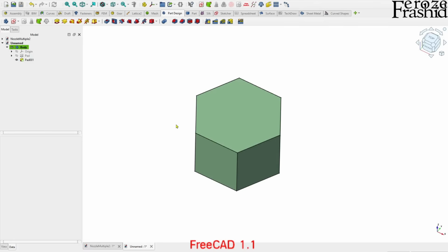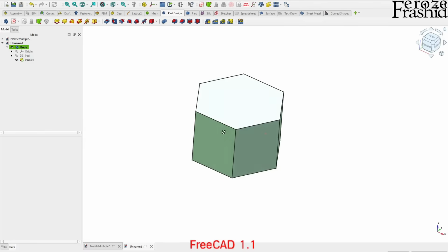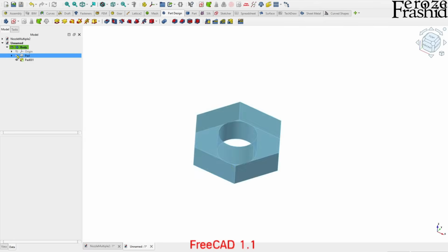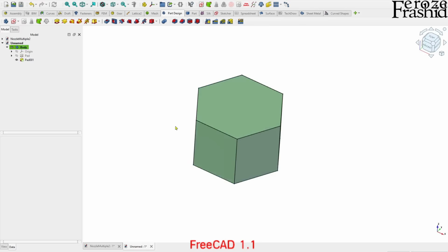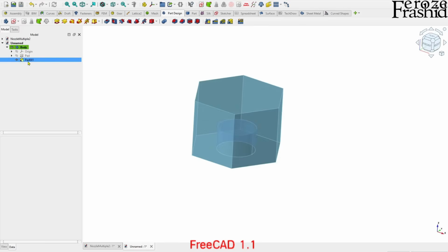So in FreeCAD 1.0, you can use these edges, like here I did. You can select the edges and then use them as a sketch when padding and subtracting. So that's a good thing. We didn't have to draw another sketch. We just took the edges and then padded it up.